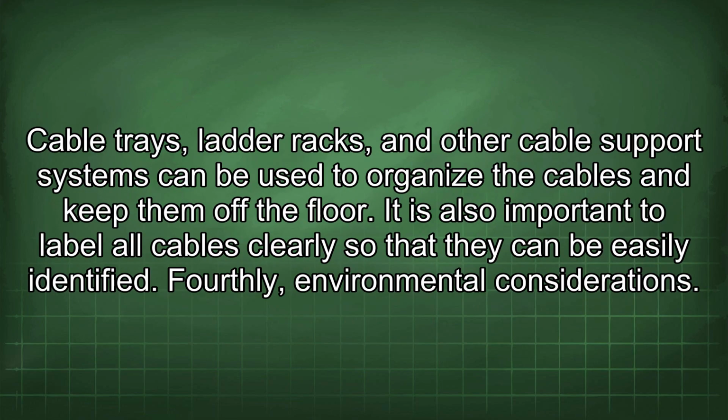Cable trays, ladder racks, and other cable support systems can be used to organize the cables and keep them off the floor. It is also important to label all cables clearly so that they can be easily identified.